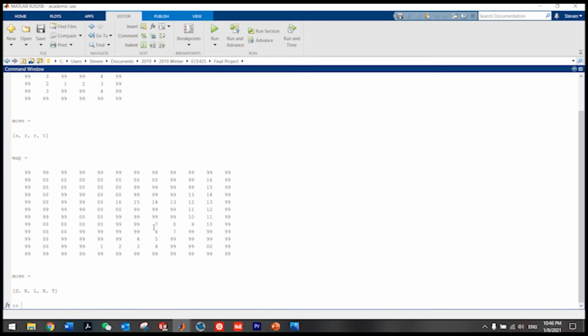That's because I'm converting the topological map into the occupancy grid, because my grass fire propagation algorithm was done in the occupancy grid instead of topological, because 1 to 15, 0 to 15, that's a lot of cases, so it's easier just to take charge of 0 or 99.